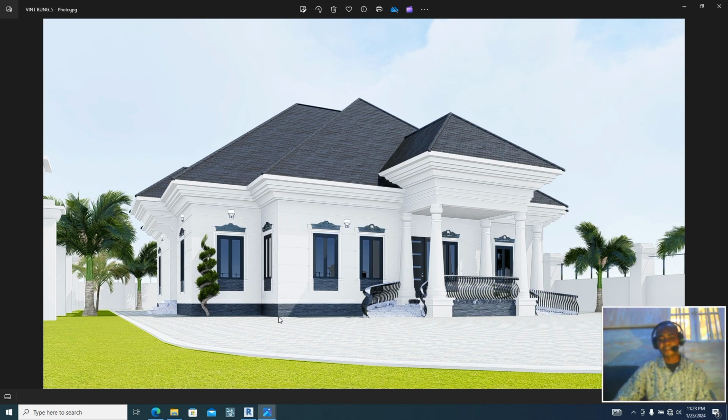It is minus any depth of your foundation. It can be 900 millimeter, it can be 1200 millimeter, depending on the structural analysis that you wish to apply. So please, the next level here from the ground level will be a positive figure, and it depends on our choice of DPC heights.